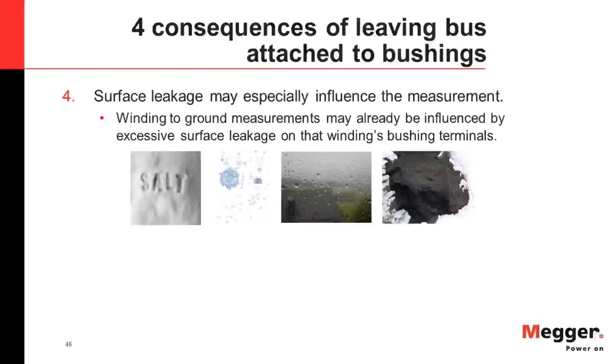Well, now if you append the measurement and now include the bus and all of its supports, the exposed surface area of the insulation included in the measurement increases. So surface leakage may have an even bigger influence on your measurement than before.